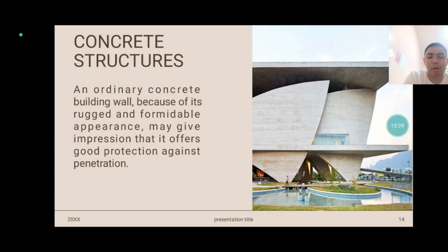However, a small amount of explosive supplemented by hand tools can quickly penetrate them. Walls thicker than 8 inches are usually for vault construction. Standard concrete block walls without reinforcement materials are easily penetrated with hand tools, power tools and explosives. The strength of these walls is increased materially by filling the hollow cores and installing rebars.